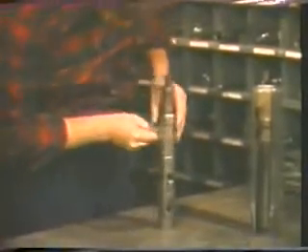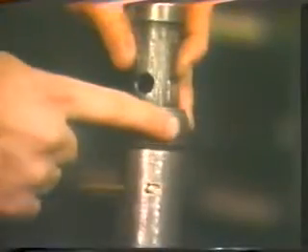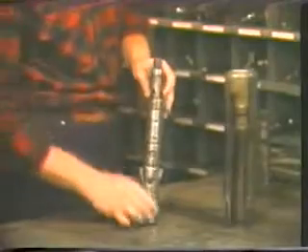If the lock assembly is to be run to the uppermost F nipple of its size in the tubing, a locator ring, which will no-go in the nipple, is threaded onto the running tool. The lock is then lowered into the well bore on wireline until the nipple is located with the locator ring. Pulling the tools up allows the up-facing locking dogs to snap into the nipple profile.